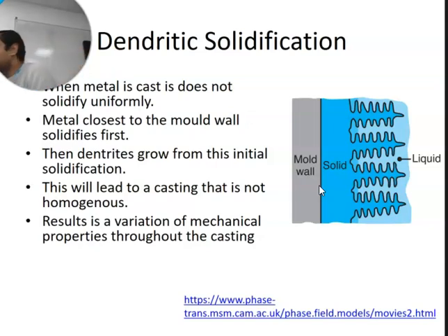Now, if we look at liquid diffusion: if you have cold water and you drop in ink, you can see the ink diffusing into the water. You can do the same with hot water; drop in ink and the ink will diffuse faster. A similar thing happens in solids. There is a thing called solid diffusion. Solid diffusion is the same thing, but it happens a lot slower than liquid diffusion.